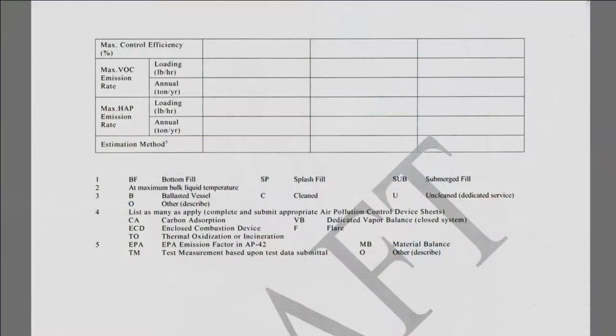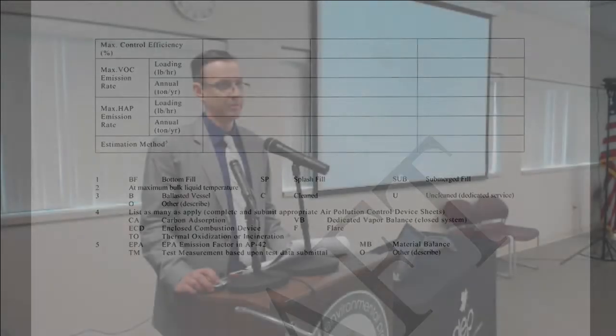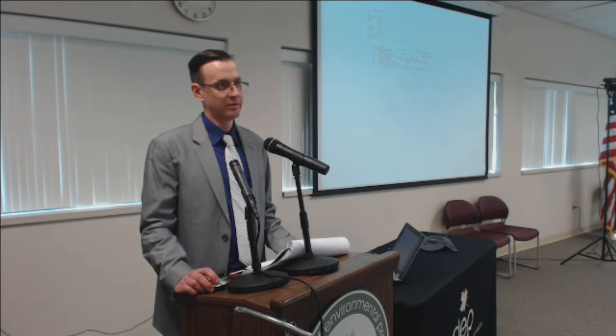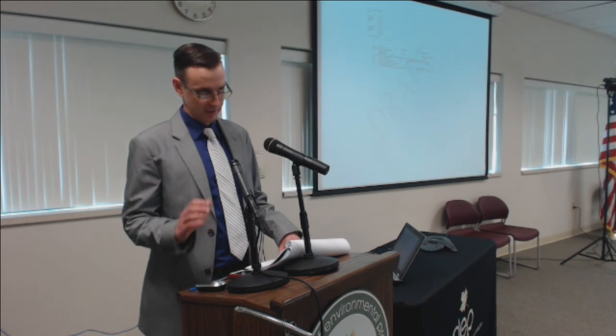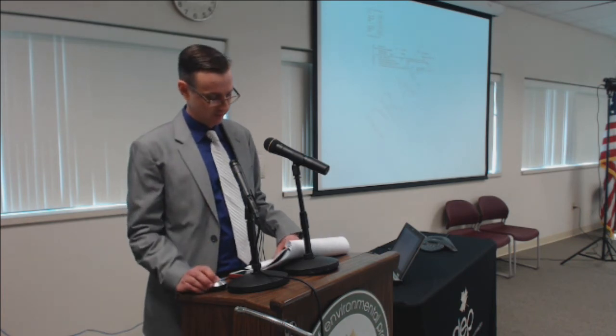And that form carries over onto page 24. At that point in time, that's where you'll indicate what your maximum VOC and HAP emissions are. And you need to provide both. More than 50% of the time, we're told there are no HAPs. So we have to push the issue and ask them what the HAP emissions are. I know sometimes they may be minuscule, and I'm not trying to say that anybody thinks they don't matter, but you need to indicate what those values are.